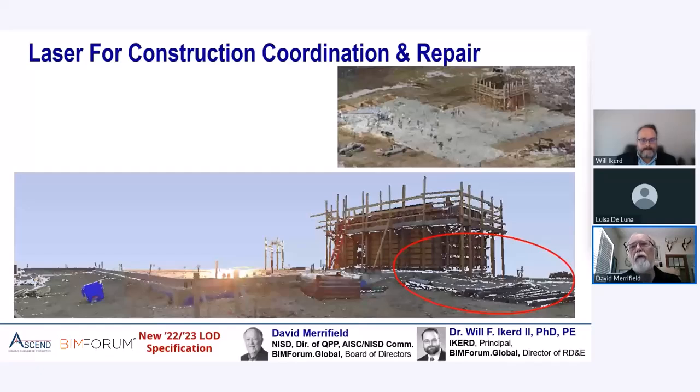The problem with anchor bolts obviously is a steel fabricator and their detailing partner will take them to a level of LOD 400, but they get shipped to the field and they're replaced by a concrete subcontractor who basically has their own set of tolerances and their own set of problems.